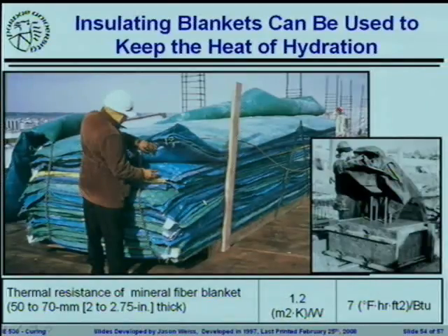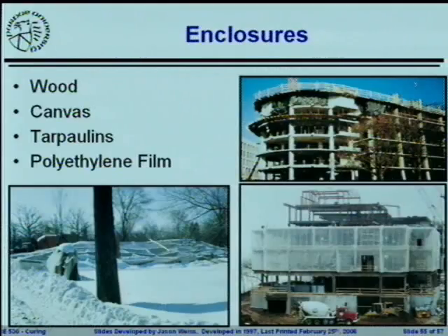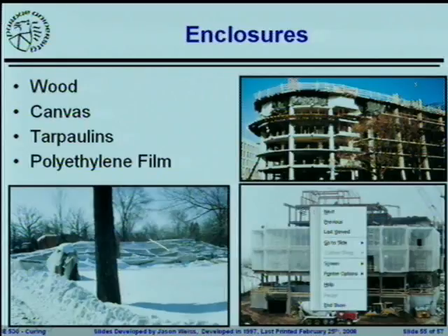So, basic idea, just like you would want a blanket if you were sleeping outside, while the concrete's sleeping, it wants a blanket so it can retain some of the heat that's generated during hydration. Enclosures, we've talked a little bit about these.